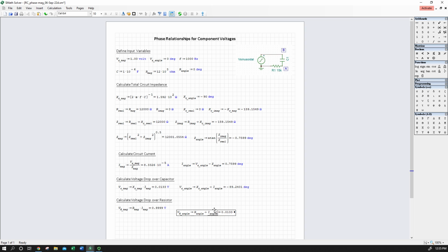And we have a positive number, which, of course, SMath wants to give us in radians, so we say, nope, give me that number in degrees. And again, this shouldn't be surprising, we have less than 1 degree, but it's positive. So let's look back up here. Our total impedance was negative, and now we have something positive.